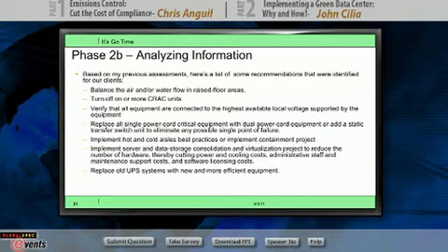It's very important because you're going to lose less energy for the same thing. Therefore, if you're running a machine or a sample server at 120 volts, and you have the capability to connect to 208 volts, and the server can support that capability, we strongly suggest that you go after that and simply connect to 208 volts, which is usually no cost to you.